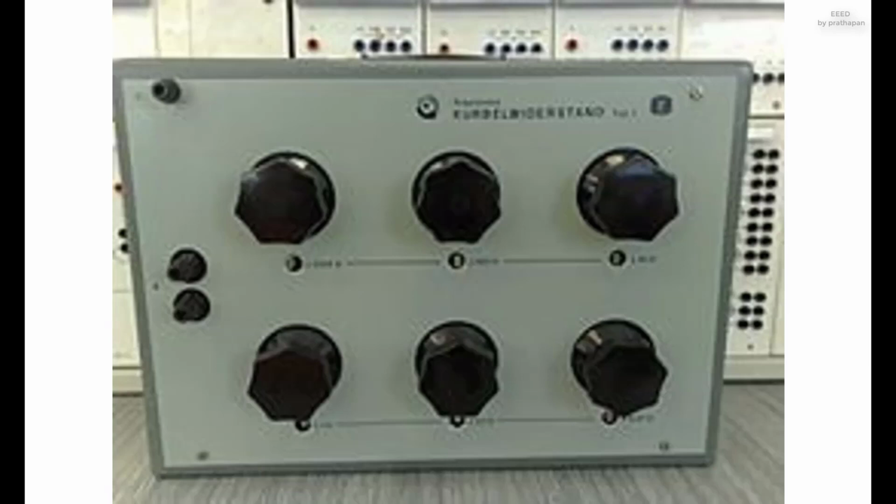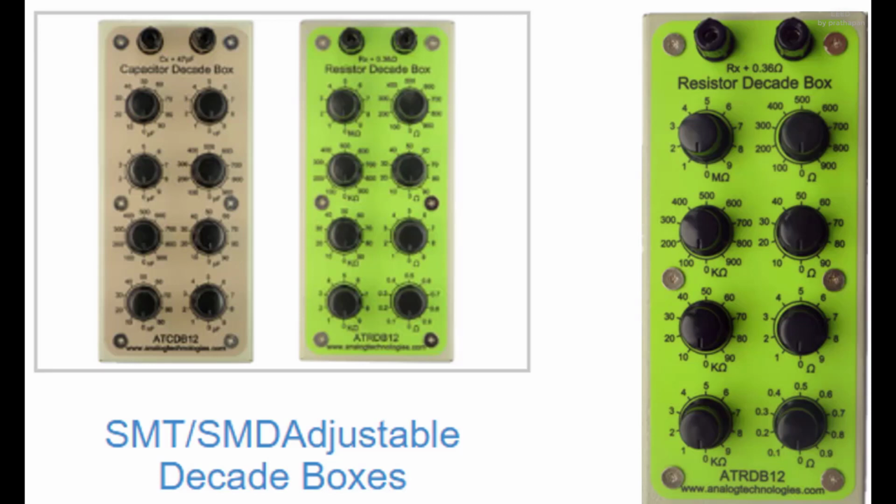Main article, Decade box. Resistance decade box Kurbel-Wider stand, made in former East Germany. A resistance decade box or resistor substitution box is a unit containing resistors of many values, with one or more mechanical switches which allow any one of various discrete resistances offered by the box to be dialed in. Usually the resistance is accurate to high precision, ranging from laboratory/calibration grade accuracy of 20 parts per million, to field grade at 1%. Inexpensive boxes with lesser accuracy are also available.